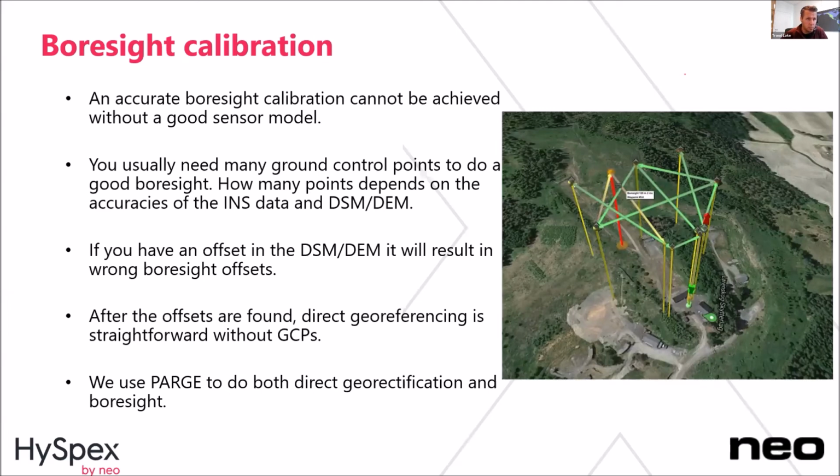I will go through this tomorrow, other options as well. Based on that data, you can calculate the boresight angles of your system. The reason you do 4 is because you want to do 4 boresight calibrations to check for consistency. If the boresight calibration when you're flying in one direction is different from the opposite way, then it means that you have some kind of quality issue.